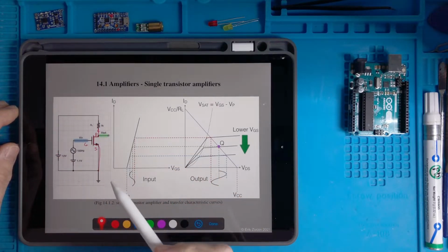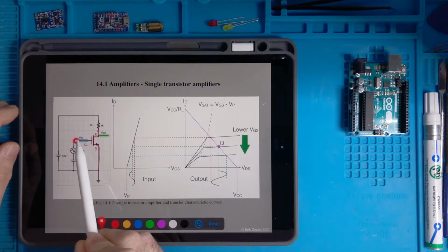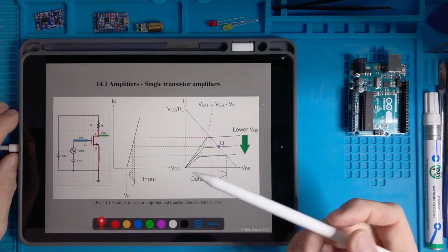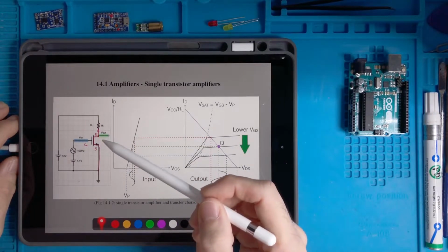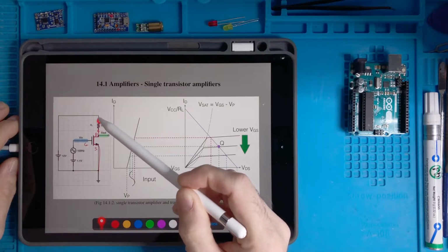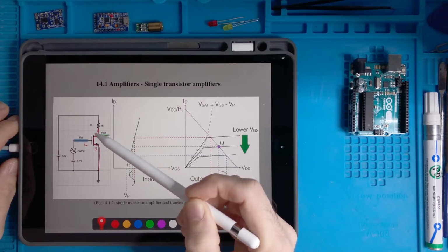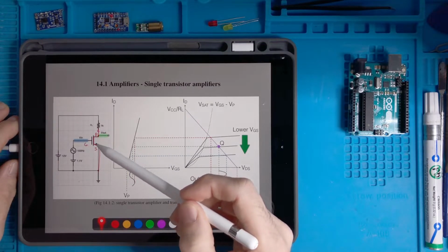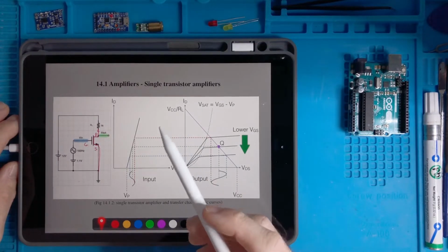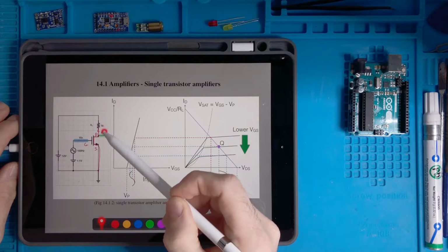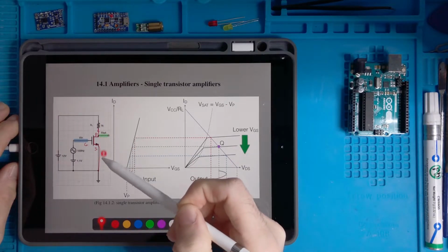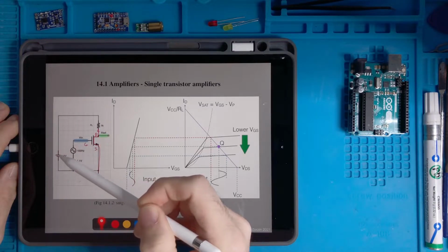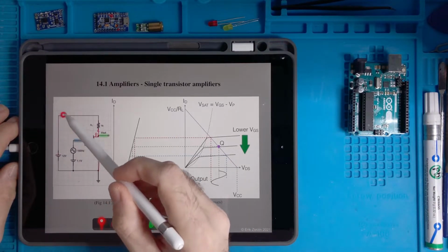And we said that the flux of this current is controlled by the voltage applied to this third terminal, which is called gate. So now we have to consider a couple of things. The first one is that there is a voltage drop across this resistor, and there also is a voltage drop across the transistor, what is called VDS, V drain source. And this voltage drop plus the voltage drop across the transistor should be equal to the voltage generated by the battery, by this battery here. And this is the Kirchhoff principle applied to this mesh.